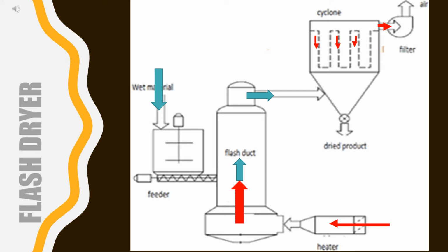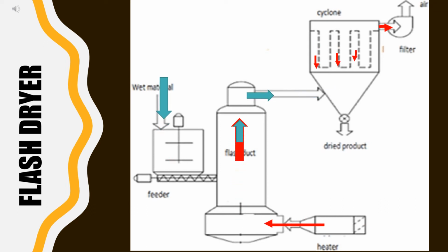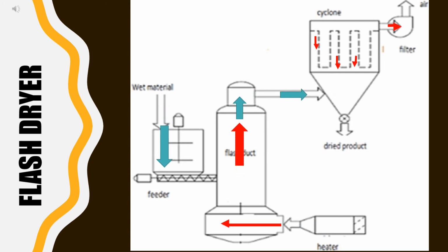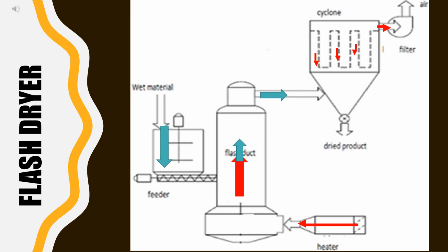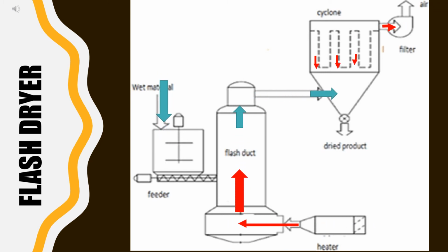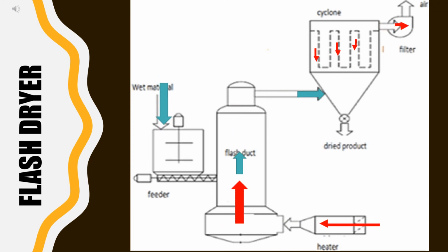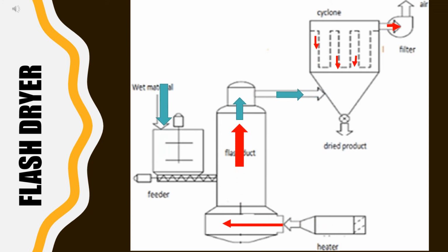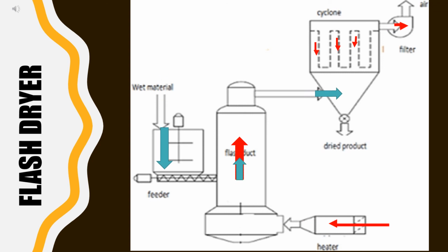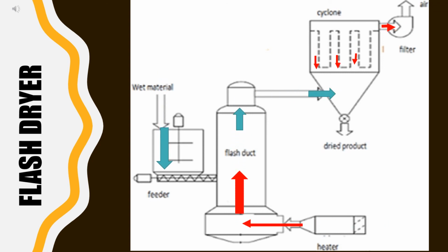How does a flash dryer work? So let's go to the principle of the flash dryer. Flash drying works on the principle of pneumatic transport using hot air. Wet product is introduced into a high-velocity airstream through a special venturi feeder. Highly turbulent airflow generates an intense gas-solid thermal exchange, and this disaggregates the product. This allows a rapid evaporation in a few seconds of residence time.